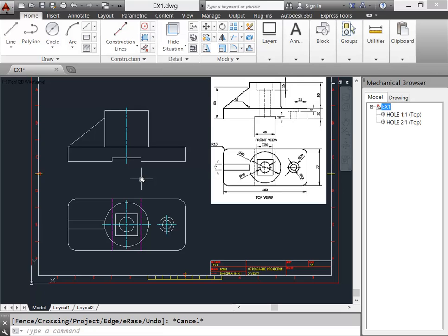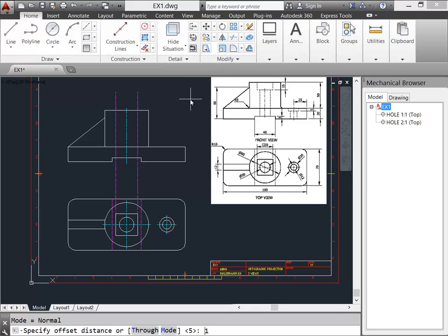Okay. Let us project our rectangle. Again, I'll take line, up, enter, from the other end of my rectangle, and I'll see that my rectangle here goes down 15 millimeter. So I'll take an offset tool, write down 15, enter, I'll pick this line and make it down.